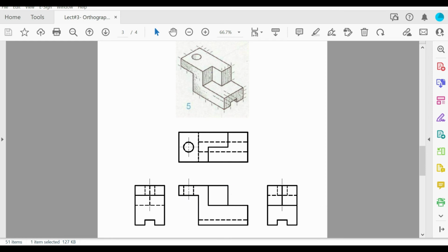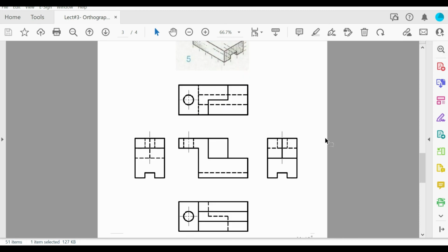And the same relationship between the top and bottom view. So guys, this is the symmetry line. So the relation between them, same relation, mirror. So if you have the top view, you can get it easily. Just mirror it down to get the bottom view. This is the top view. And same idea, you have to check each edge.